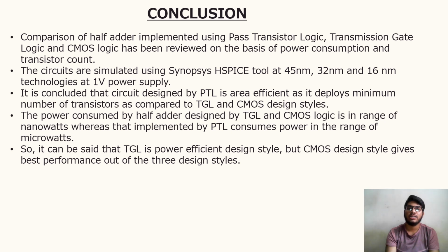Comparison of the half adder implemented using pass transistor logic, transmission gate logic, and CMOS logic has been reviewed on the basis of power consumption and transistor count. The circuits are simulated using the Synopsys HSPICE tool at 45 nanometer, 32 nanometer, and 16 nanometer technologies at 1 volt power supply. It is concluded that the circuit designed by PTL is area efficient as it deploys the minimum number of transistors as compared to TGL and CMOS design styles.